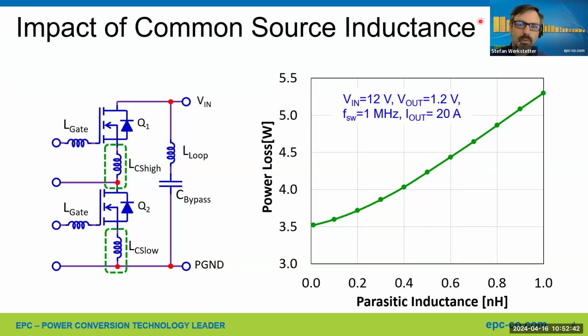Thanks, Tiziano. Then we have one question regarding competitive testing. Can I make a DIY TO220 packaging for the EPC GaN for some sort of comparative testing against MOSFET using the same board topology like DPT or half-bridge? Shall I need to worry about parasitic inductances since EPC GaN packaging is so small and the routing is very difficult? Yes, the answer is yes. Of course, it is a big trade-off, but it is possible, and some customers did it.